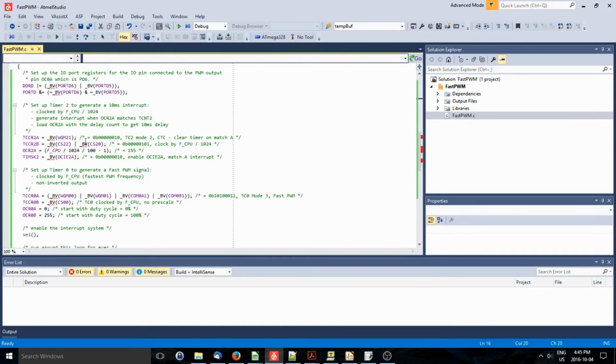And what I did here in this case is I used actual defined constants for setting the bits. Again, you could just use this binary notation, but this guarantees accuracy and this does not, because you don't know exactly which bit you're setting. You could make a mistake in your counting, and this is more or less error prone. So I did it the same way for all of these.